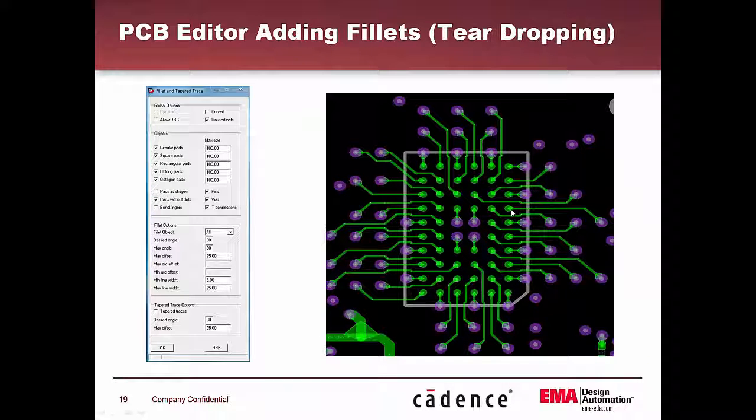Well, what happens is when you get into these type of fine line designs, whenever you have a very fine line coming into the entry of a pad, we have a very sharp entry point which comes into that very small pad. And this can potentially create a reliability issue, because if the board is subject to any kind of vibration, or depending on the environment that it's in, you can actually have what they call a fracture point occur where this trace enters the pad.